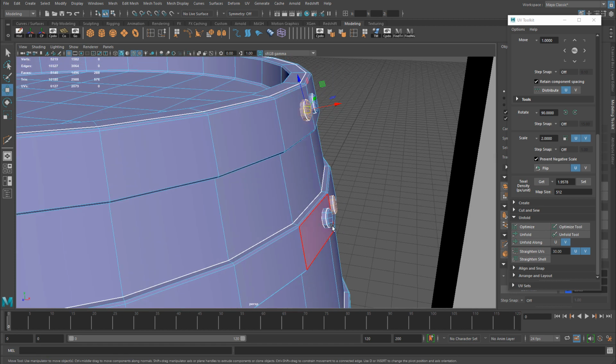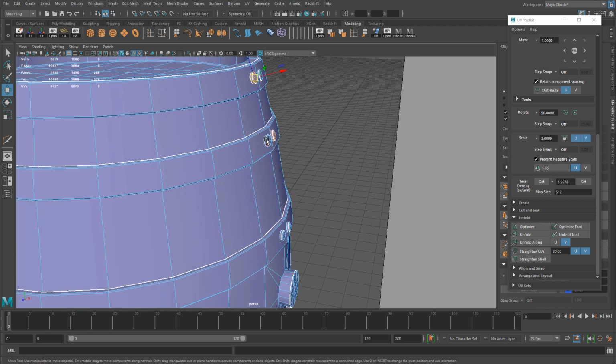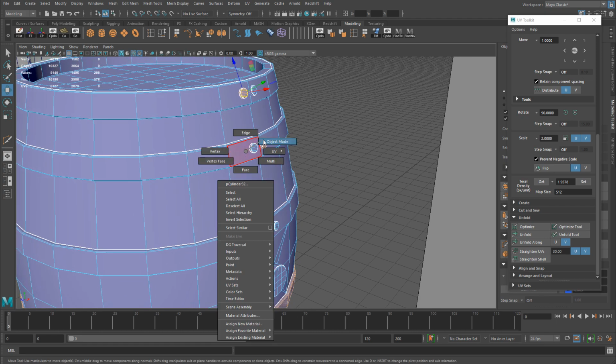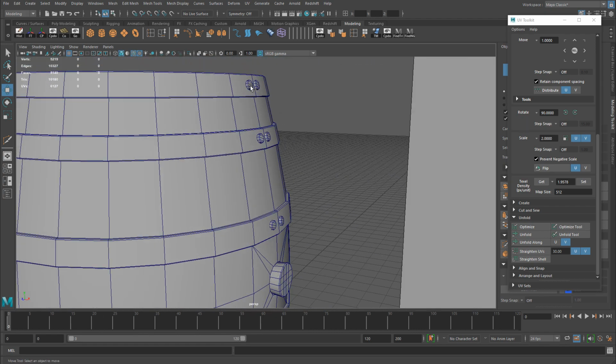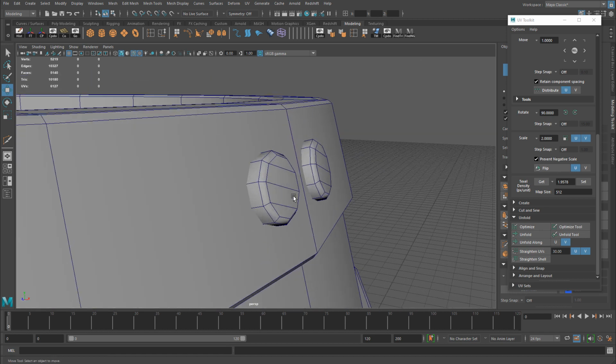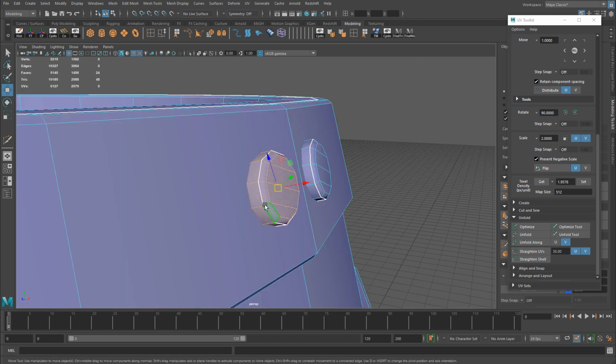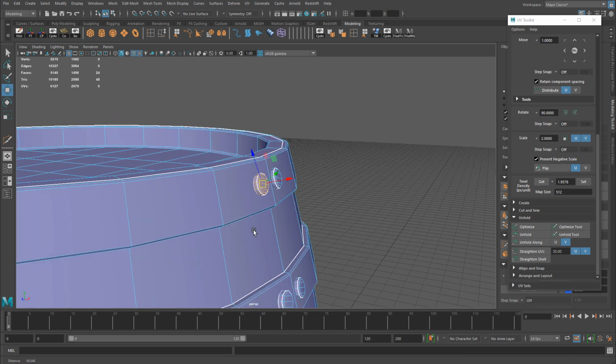Those little bolts that you see, little straps that keep the metal ring together and attached. So I introduced that piece of geometry. Instead of doing it through a normal map, which I thought I wanted to do, but I decided not to, I just simply created an 8-sided cylinder, beveled the corner just once, cleaned it up, UV'd, and then duplicated all the way down across.